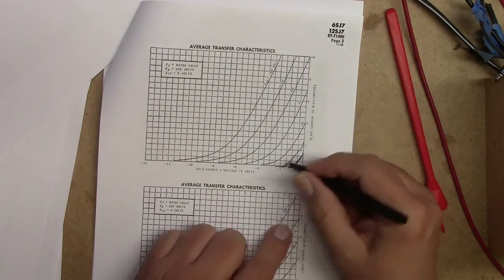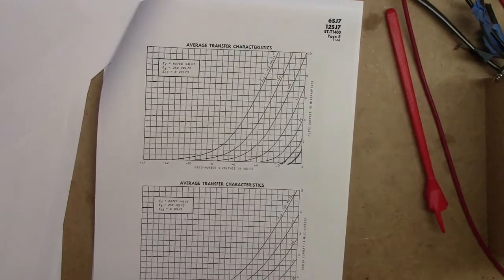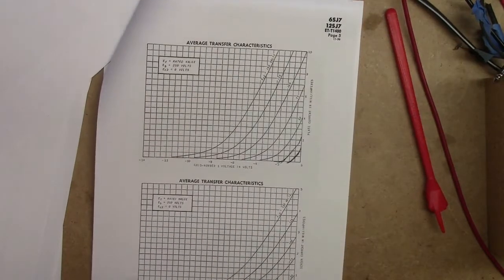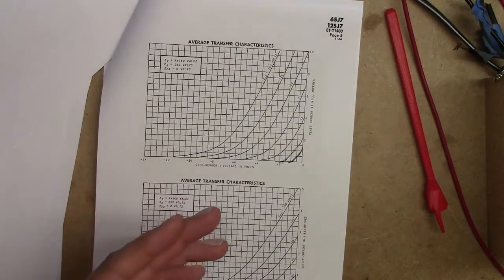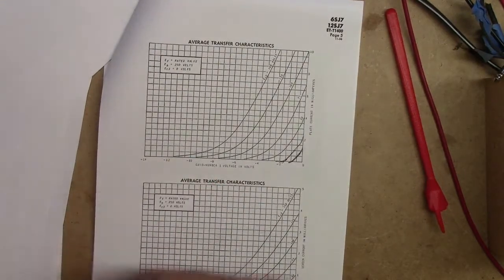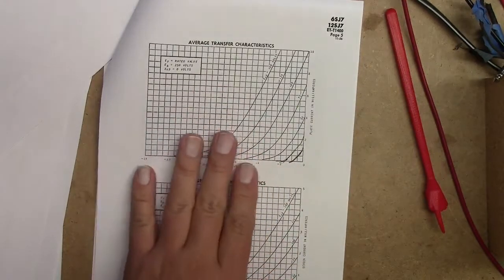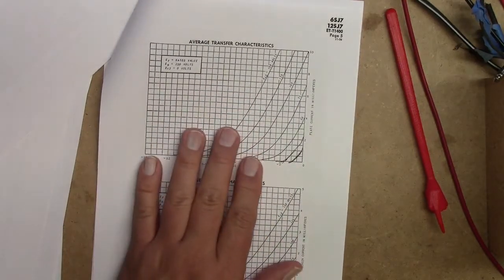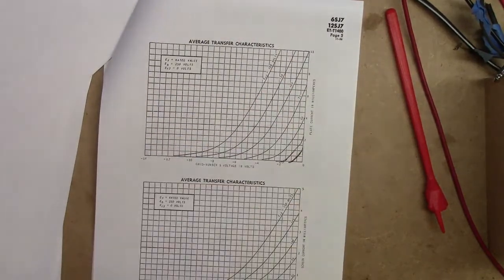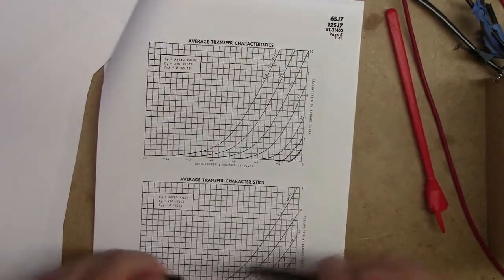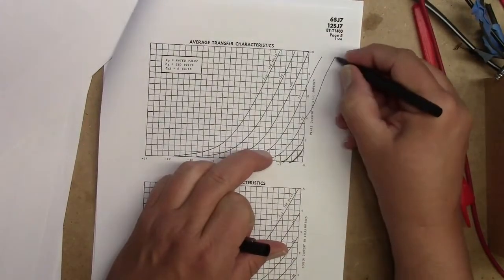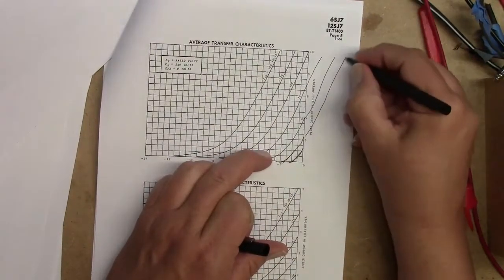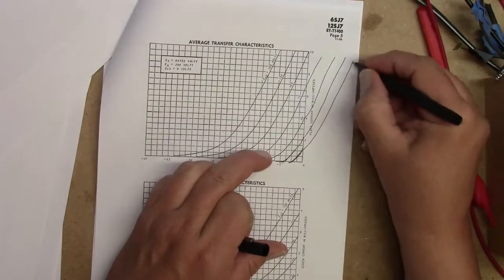Now this is a small signal pentode, so they don't recommend you do positive grid biasing where you'll have grid current. But if you were to look at tubes that are pentodes that are designed to handle grid current, these curves actually continue over on this side of the y-axis, and they all have pretty much the same shape when they get over here like this.